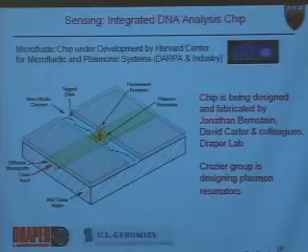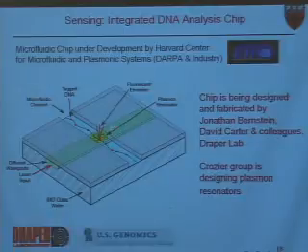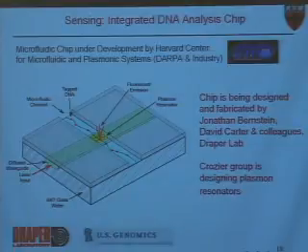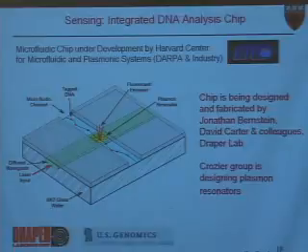Now, in this illustration, I've shown several rows of these. I mean, that's what we're doing in our initial devices, but the final device will just be a single row of plasmon resonators. We're also looking at other designs here, but basically a single row of these that generates kind of a narrow stripe of illumination, much smaller than the wavelength, and it'll excite the fluorescence from the DNA.